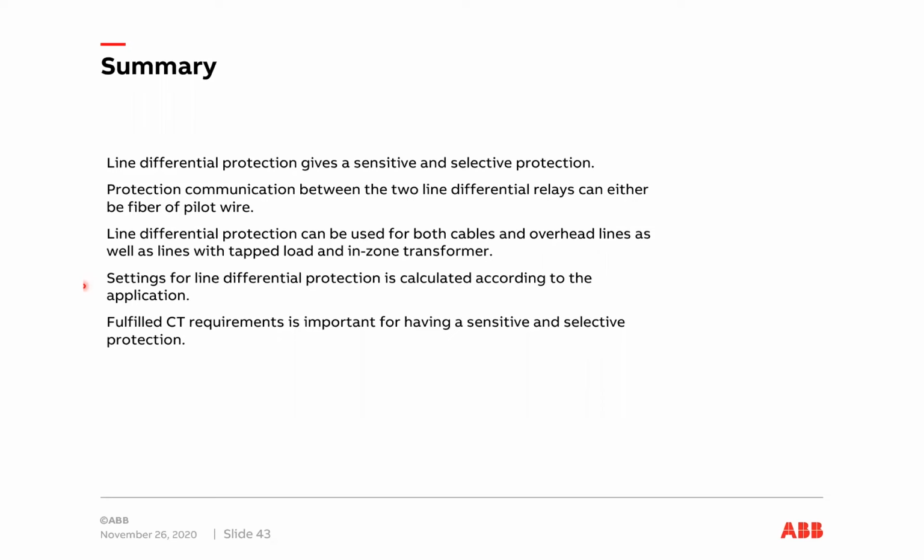It's important always to calculate the settings according to the application. So you need to look at what we are protecting. Are we protecting only a line, or does it include a tapped load or an in-zone transformer, and so on?